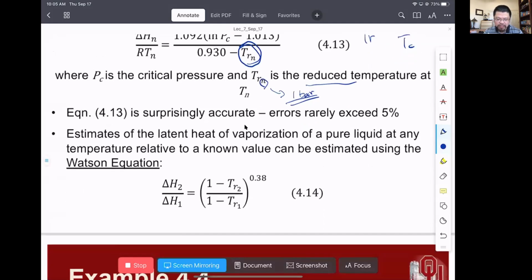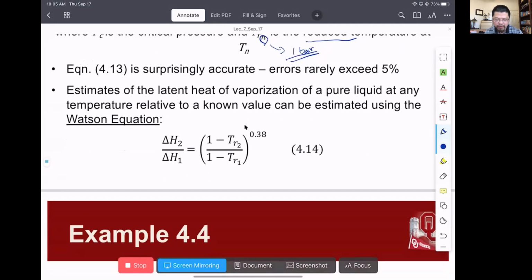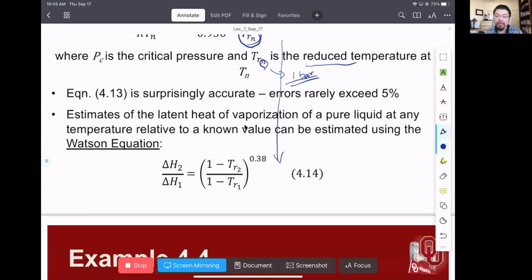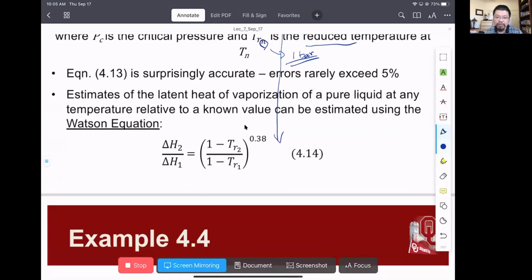And then we may have the other type of simplified form. So moving from this equation, we should be able to derive that equation. Basically, if I know the enthalpy requirement for one boiling process at a temperature or a pressure, I can easily calculate what would be the enthalpy needed for another temperature or pressure by using this empirical correlation.